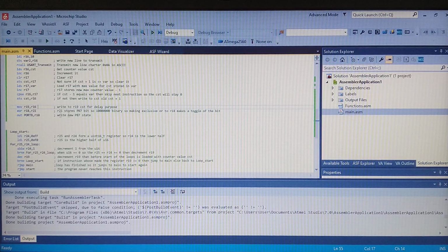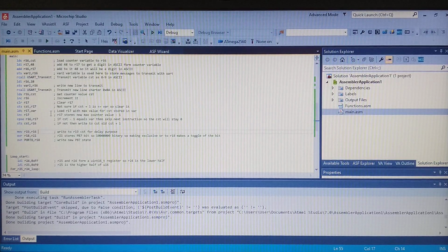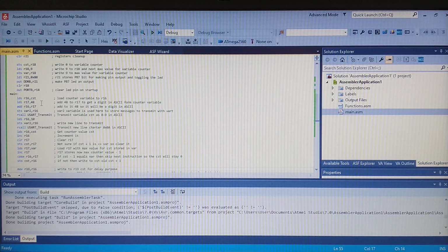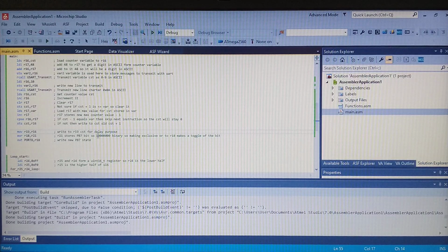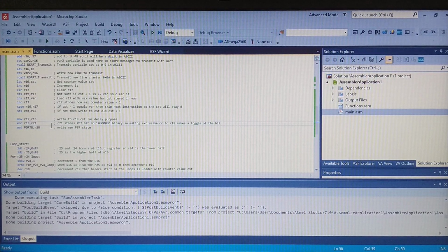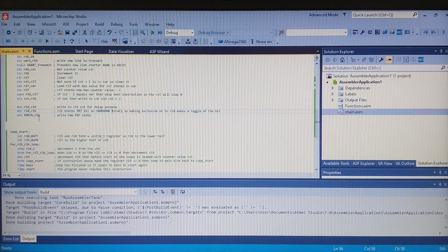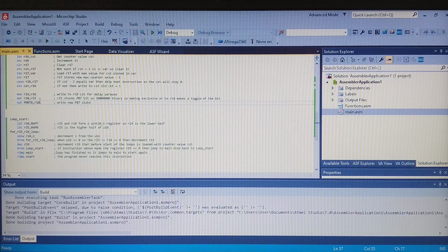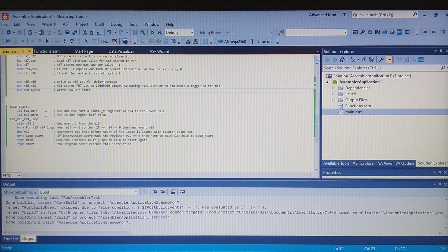So as you remember, in R21 we got the bit value for the LED, which is this value, and making an exclusive OR, we simply make a toggle to the LED, so PB7, by writing into the port B. Okay, so now as we got this done, next on we jump to the loop start.